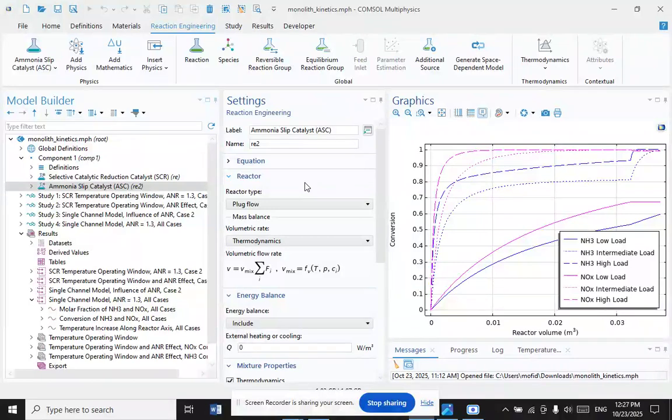This is known as filter regeneration, and cleaning is also required as part of periodic maintenance, and it must be done carefully to avoid damaging the filter. Failure of fuel injectors or turbocharger resulting in contamination of the filter with raw diesel or engine oil can also necessitate cleaning.